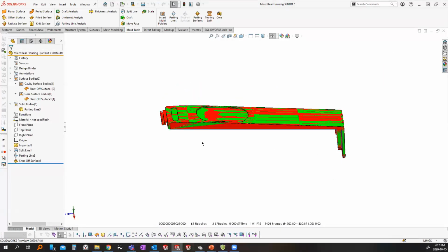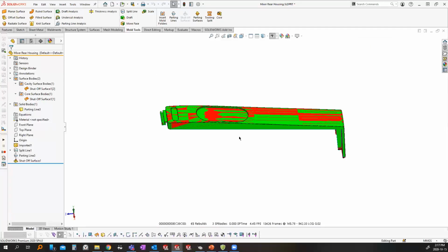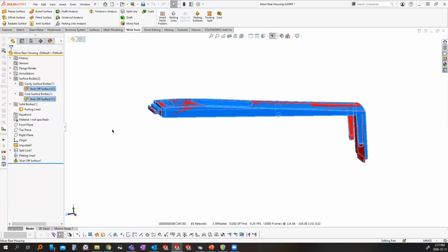I use the isolate command so much, actually, that I went and set it to some hotkeys. So I just picked whatever keys make sense to me and aren't being used for something default. In this case, I for isolate, and the key right beside it for unisolate. So you'll see me using those throughout the webinar. So I'll just isolate these two for now.